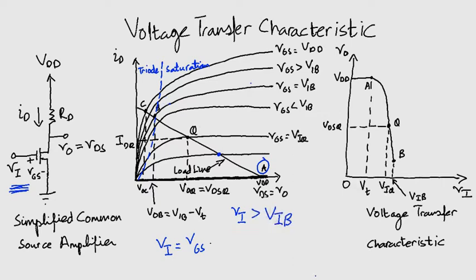We continue to go up the load line from B to C in the middle figure. In the corresponding voltage transfer characteristic, we can draw this by the segment BC, and when we reach the point C, the corresponding voltage at the output is going to be very small. Look here, this point, VOC. It is much smaller from where we started, VDD here. We can also see this on the voltage transfer characteristic.